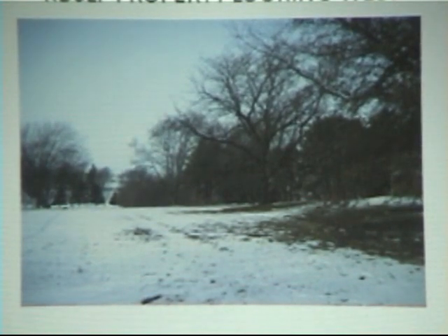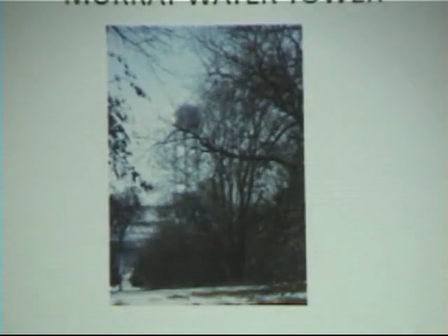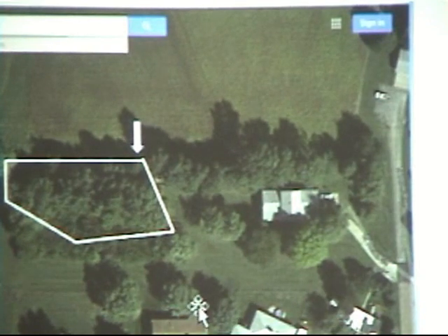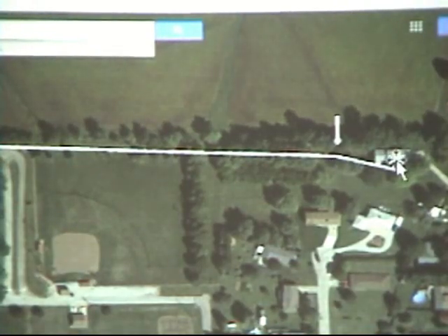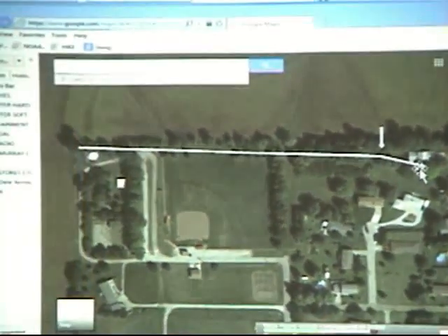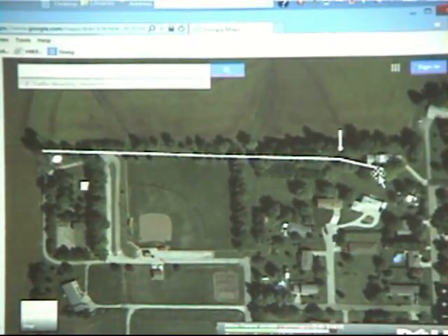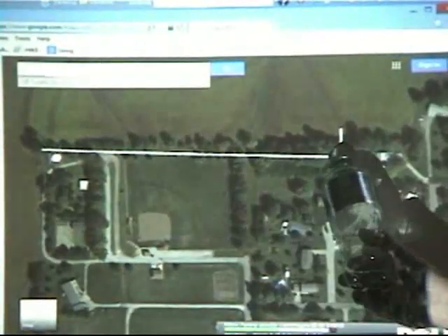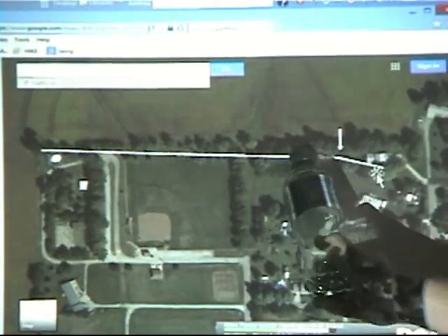So here was the answer to my prayer for a 160-meter antenna, that water tower. I got Kevin to climb the tower, and I strung 1,000 foot of wire. That's like 170, 180 bucks worth of THHN from Menards. And I strung it. I fed it a quarter wave in from the end, so this much is a dipole, which I use now.